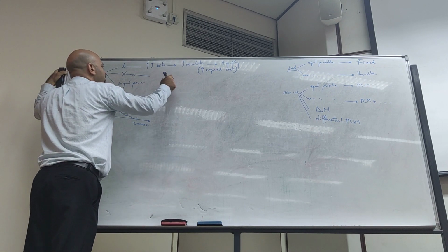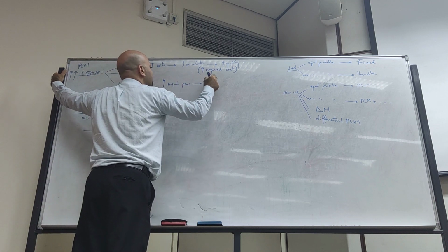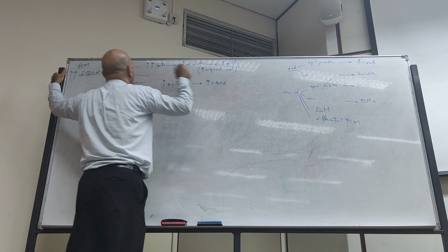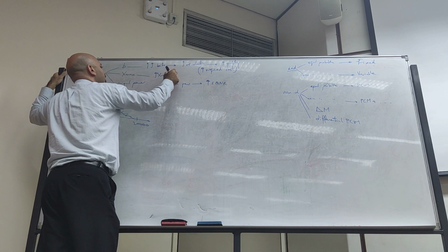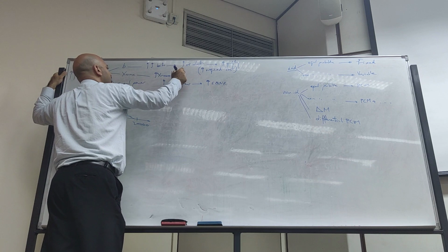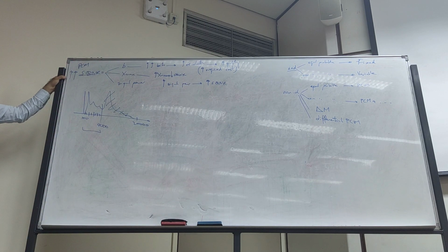But increasing the signal power is not for free. Here, increasing the signal power will increase the SQNR. Here I should have added that increasing the X max will decrease the SQNR. Good. Increasing the signal power will increase the SQNR, but again here we have to be careful.